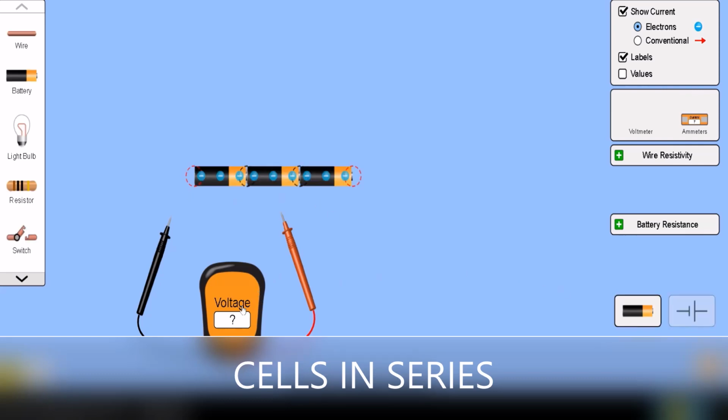Now if I measure the voltage across each cell, it will come out to be 9 volts. So this is the negative end and this is the positive end of the first cell. It is showing 9 volts, right? But if I join the positive end of this cell with the red end of the voltmeter, then you can easily see that it is now 18 volts because these two have been joined in series.